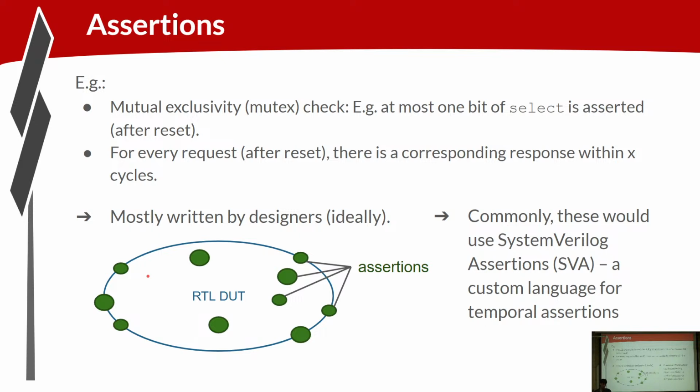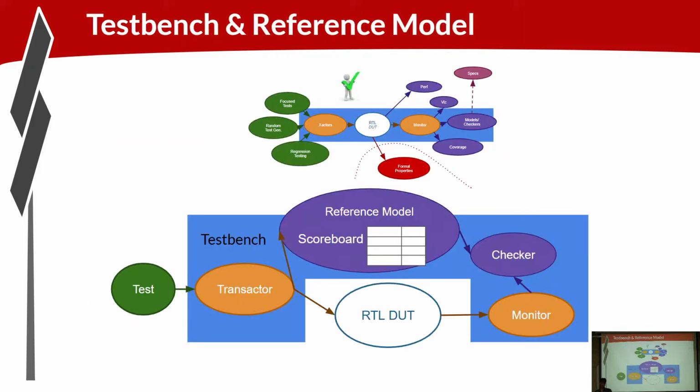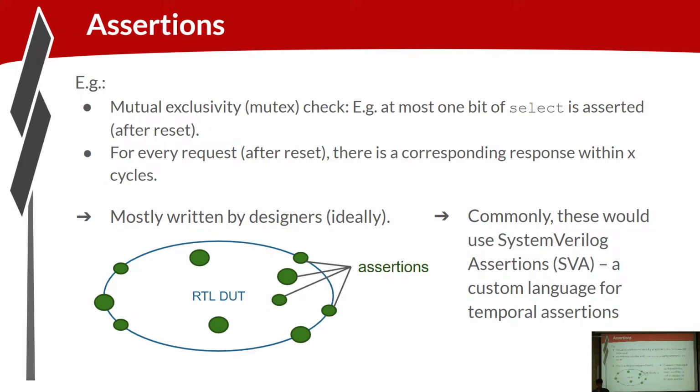Assertions are very low-level checks that might be internal in your design, right? A lot of our verification is focused on treating something, for the most part, as a black box. So you don't care how it's getting done, what's happening internally. You just want to make sure that the behavior that you're seeing from the outside is right. Assertions, they can be internal. You sprinkle them everywhere. Assertions are not your level of completeness for verification.